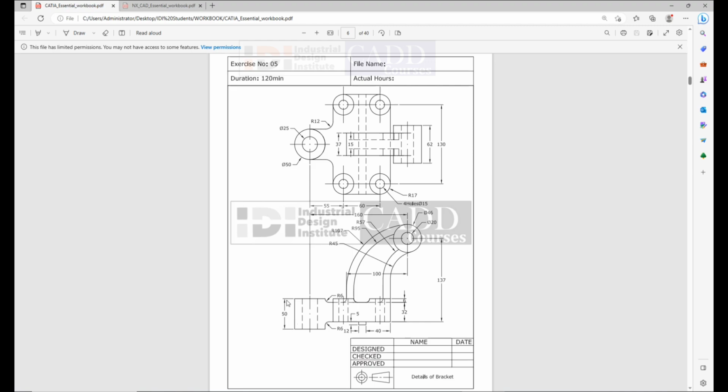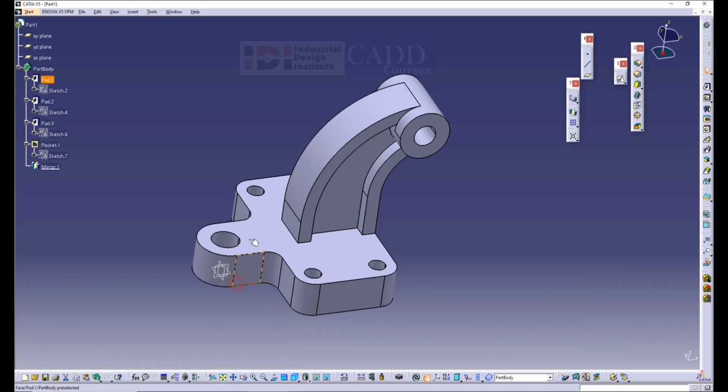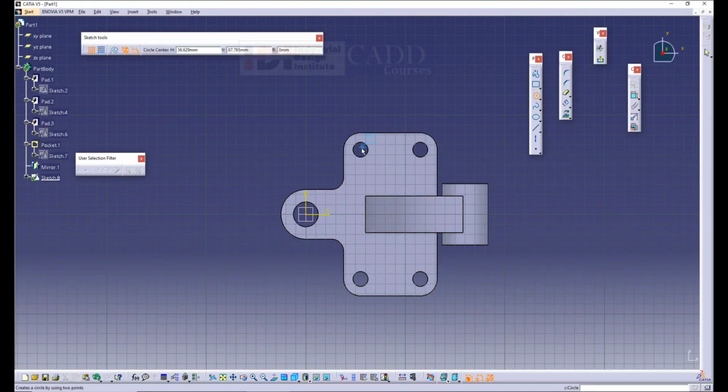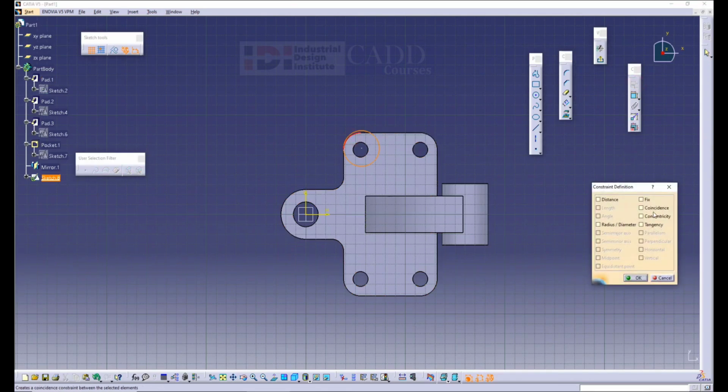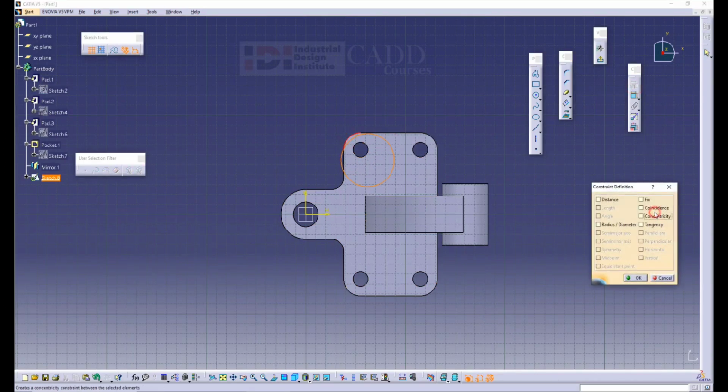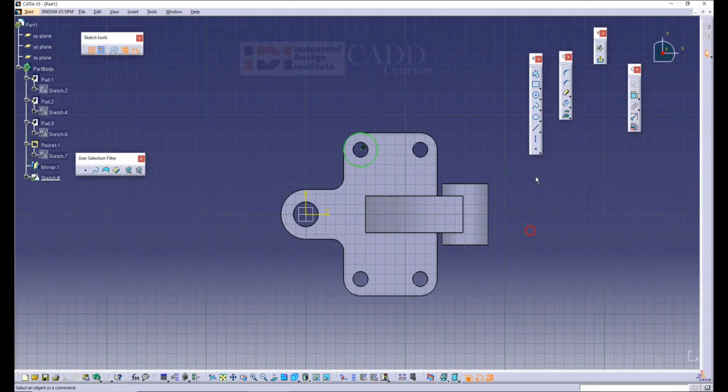So I want to create this 50 mm shaft. It needs to be extruded, I mean padded. Create a sketch with respect to it. So I'll create a sketch. I'll give a concentricity. I'll try to give a coincidence first. This is one. Coincidence, it takes the exact parameter which I need.